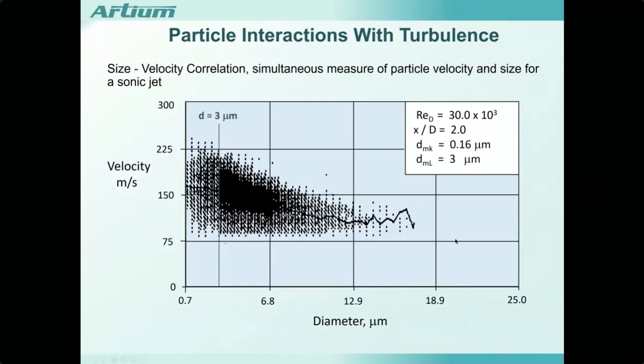So you might say, well, that's an interesting analysis. How well does it work? With the development of the phase Doppler interferometer, we're able to make particle size and velocity measurements simultaneously. In fact, part of what drove my invention of that method was the idea that if we could measure the particle size simultaneously with the velocity, I could discriminate out particles that were too large from my turbulence flow measurements and hence improve the reliability of the measurements.